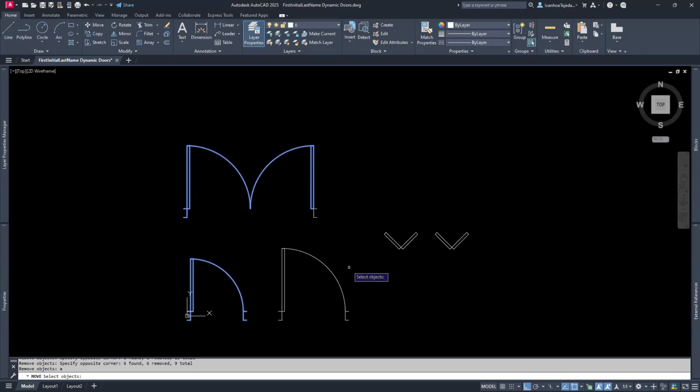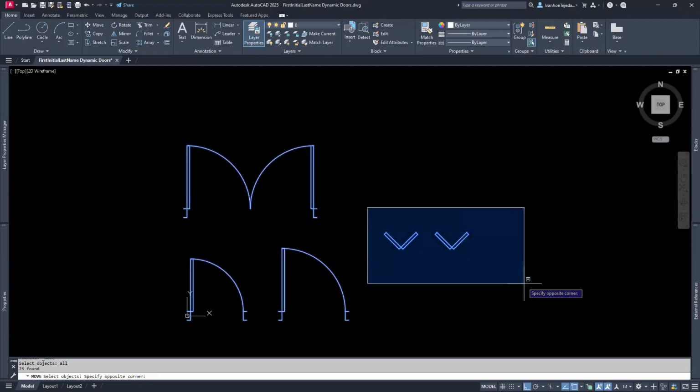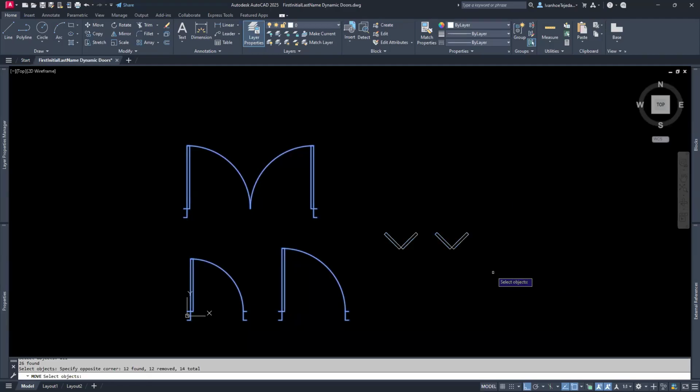So that's really nice. Let me tap the escape key and then show you one other thing here when it comes to selecting objects. And this one is pretty neat. So let's say I want to move objects, and let's say I want to move all of them. Well, just type in all, A-L-L, enter. Selects everything. But let's say I wanted to move everything except these bifold doors over here. I hold down the shift key, I click, not click and drag, I click, and then I click over here, and those objects are deselected, and everything else is good to go.